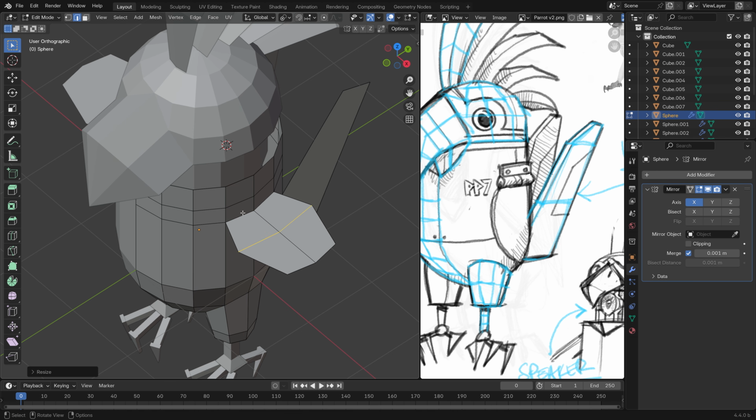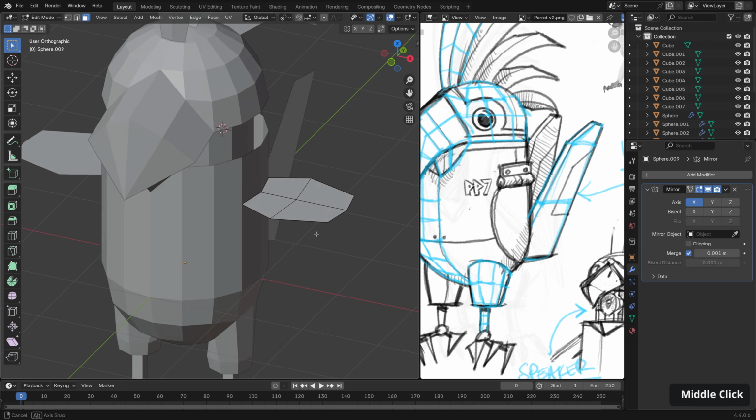Now we don't even need our wing to be attached to the geometry here, so I'm just going to go into Poly Select, select all of the wing geometry and just hit P and separate by selection so we can refine it a little further.